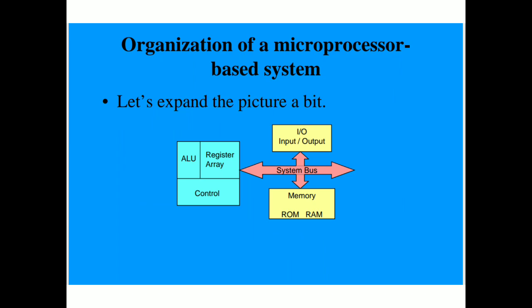So ALU is the arithmetic and logic unit, and it performs arithmetical and logical operations. Arithmetical operations performed are addition, subtraction, multiplication and division. In addition to these operations, it also takes the complement of a number, compares two numbers, rotates the bits of a number left or right, increments or decrements the number, etc.